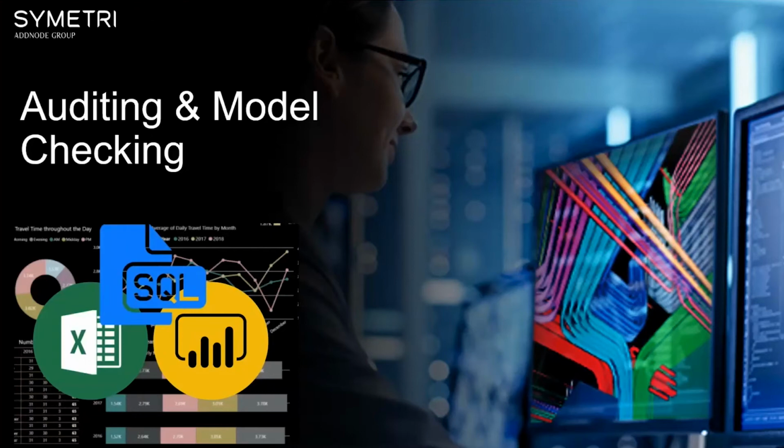Now, the three bits of software that we're using here are Revit, Dynamo, and, in this case, you can see that we've got a choice of storing the data in an Excel file or a SQL Server database. My preference here is to store this in a SQLite database and then use Power BI to produce the report. The great thing with this is we can store history. For example, if you're working on a long-term project, you can run this audit weekly, then see the statistical changes around that project.